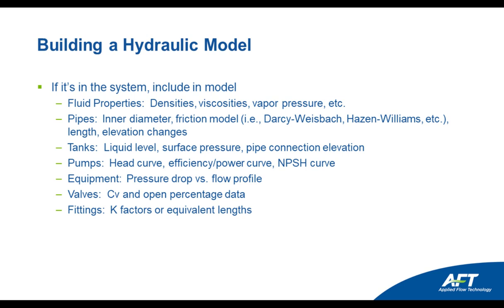This is really helpful if you're trying to model control valves in your system, and the analysis tool would be able to figure out how the control valve needs to change its pressure loss to meet set point, and then the CV and open percentage can be calculated if you include that data, which would be potentially critical to your application. Last but not least, fittings, K-factors, and equivalent lengths are certainly important to make sure that you're accounting for the minor losses in your system.